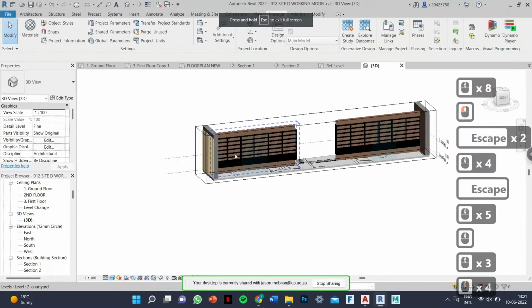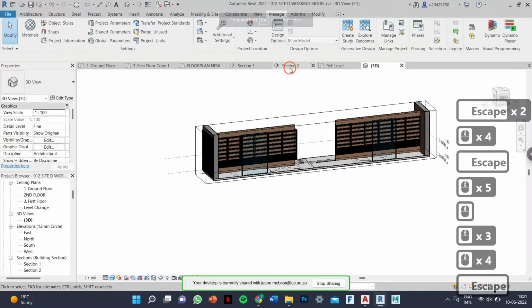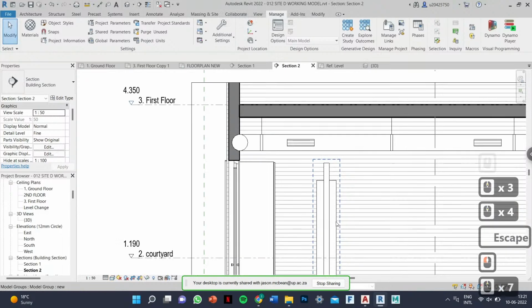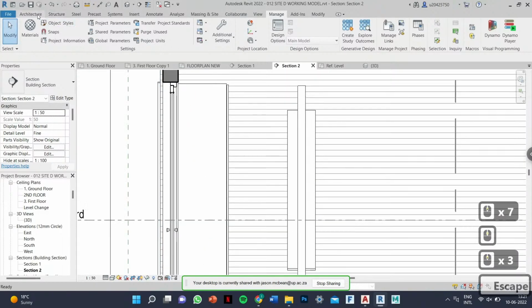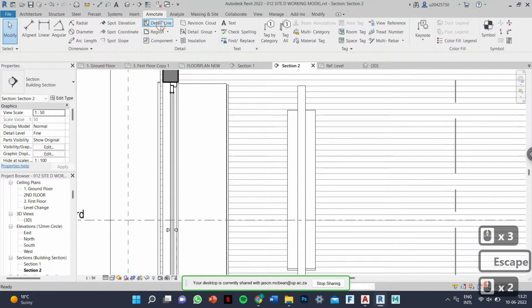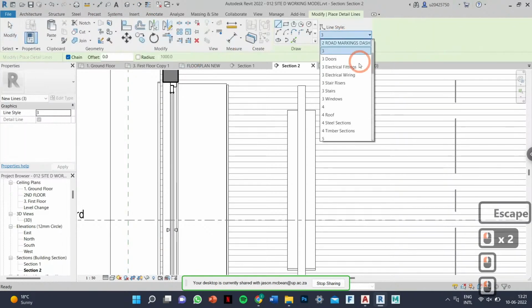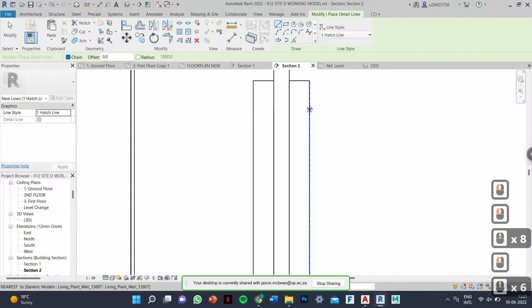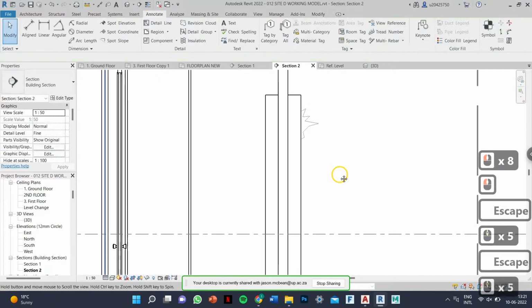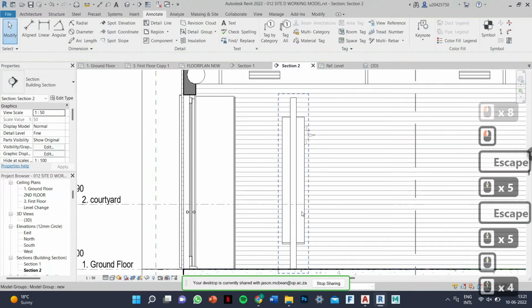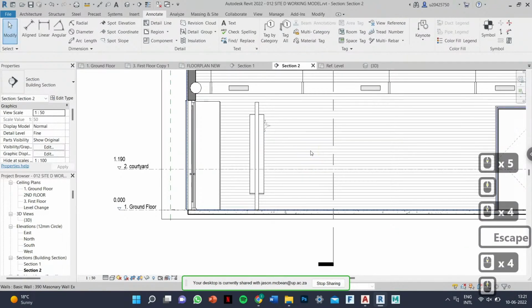Now, in section view again, let's just go to section view 2. Here you can just show a little bit of plant, you can scribble like a grey line. Here you could have actually gone to Annotate, Detail Line. There is a hatch line that we use for that, it's reserved for that. Here you can go and create a little scribble, scribble, scribble, so it kind of looks like planting. Trust me, it's purely symbology.